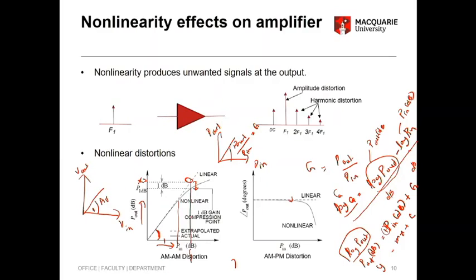So you don't really want to operate in that range, because if you operate at a higher power input, you will always get less power than you desire, right? This pretty much sets your upper limit in your output power, P1 dB, and then you tend to work at a lower power level. For LNAs, you work at lower power levels around here. But for power amplifiers, you work at higher power levels here. Anyway, that's what P1 dB is. This is just a common measure. You can't really simulate P1 dB easily. There's a way to simulate that, but in your exercise we won't really cover that.